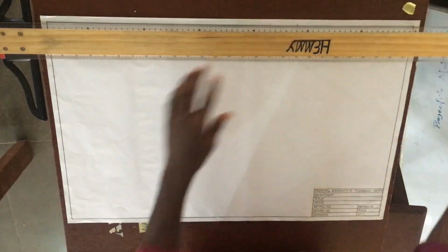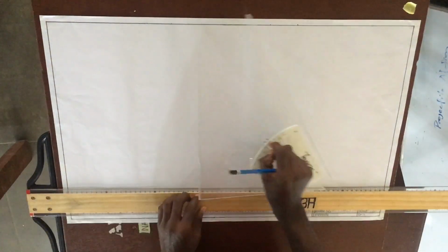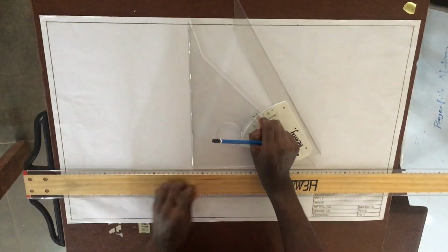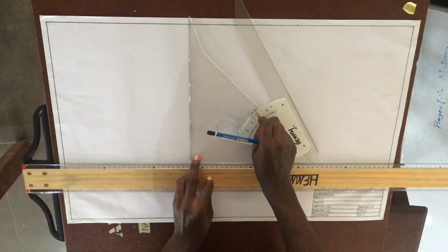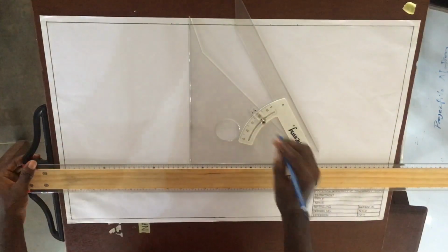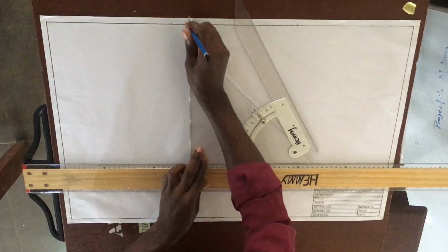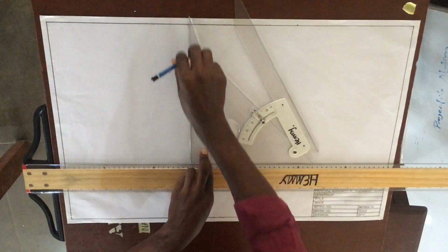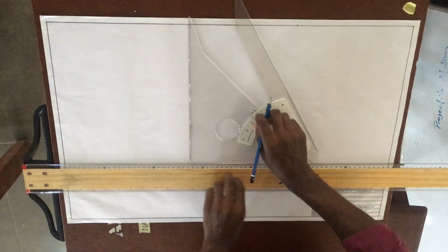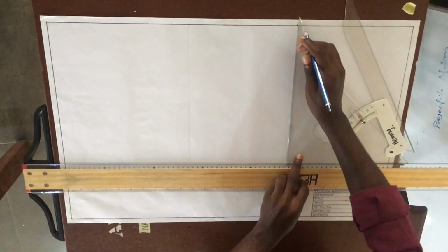Yeah, all right. So the next thing to do is we use our set square with our t square well fixed to our working edge. Draw a parallel line, just a thin line. It's just to show you demarcation. So it's a thin line.